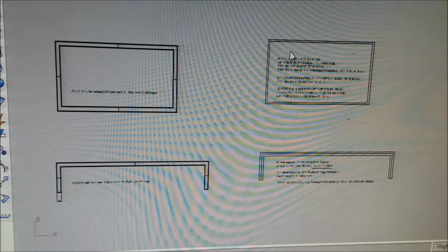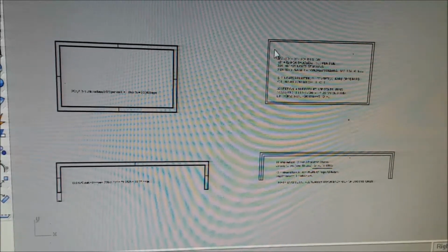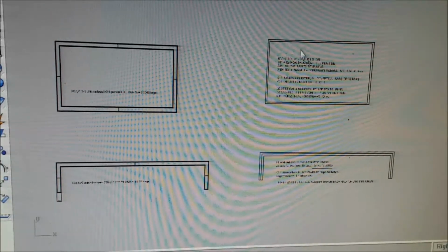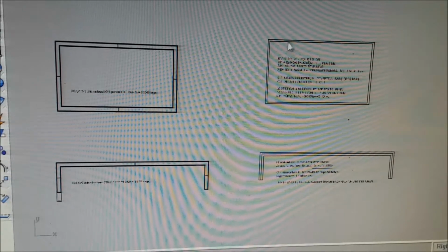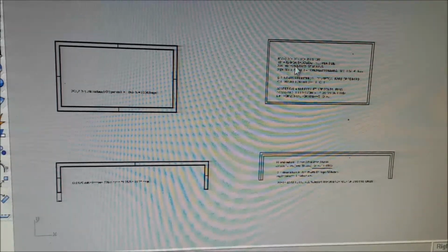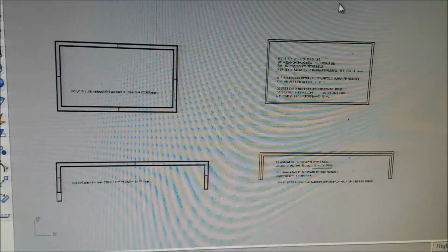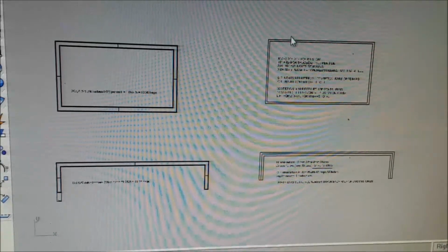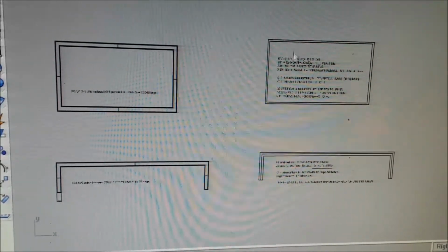The number of splices goes up slightly, not much, and then you do the other ones going this way, and what you end up with is, any place you're near an edge or where you're running over top, like if this was just one room and this was an interior wall, the only ones that cross that wall to hold it together are what would be vertical in this little drawing here.